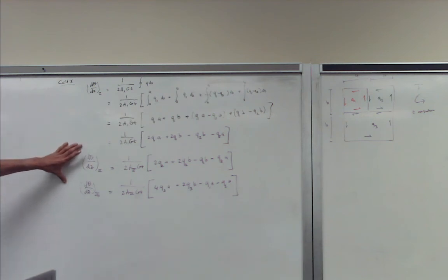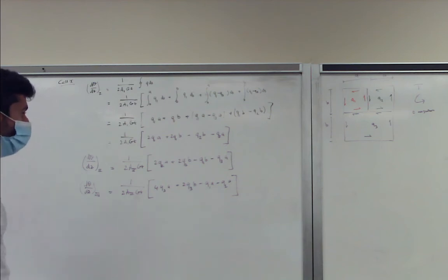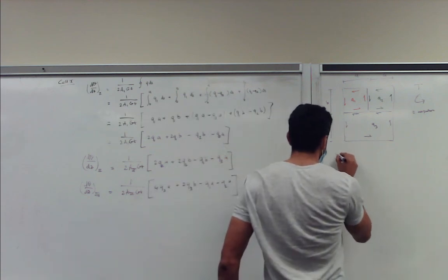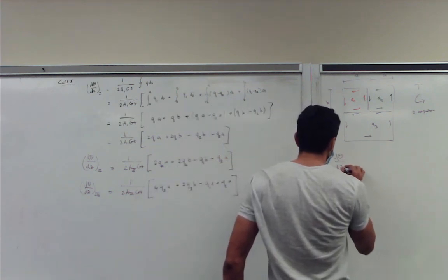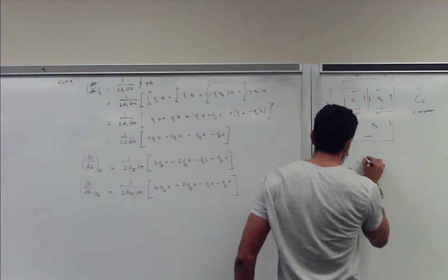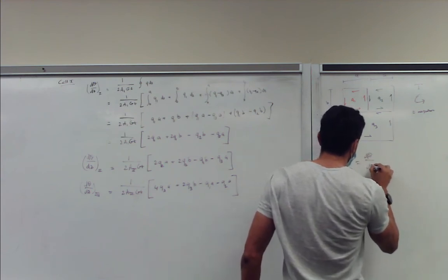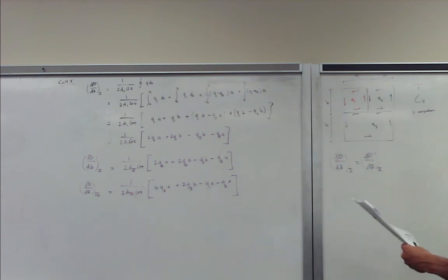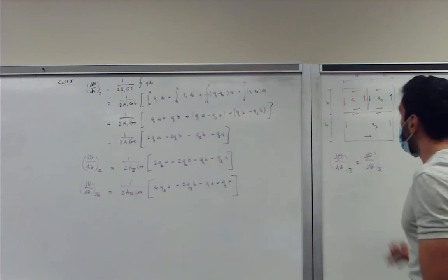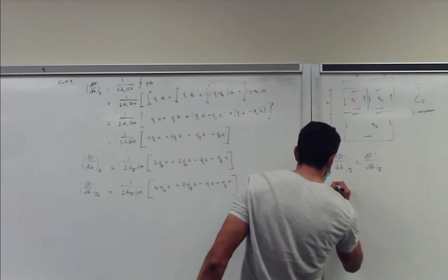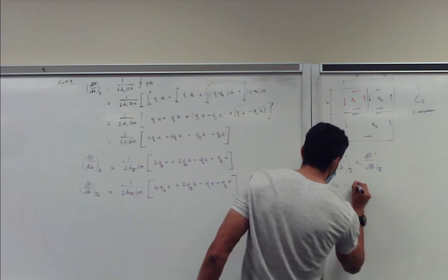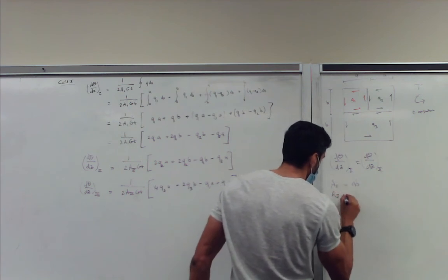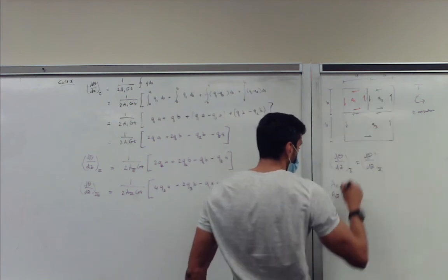So now we have 3 equations, and now we can combine those 3 equations and use the rate of twist equality. So d theta dz1 must be equal to d theta dz3, or 2 in this case, it doesn't matter. And we know that A1 is nothing else than AB, because that's the length and the width. A2 is AB as well, because length and width.